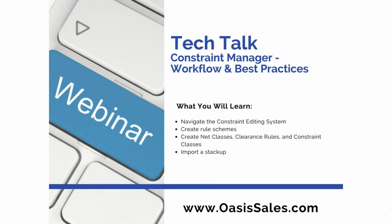So the Constraint Manager, a lot of people do find it confusing the first time that they look at it because there's a lot of information in there. Hopefully we'll learn today how to navigate that system, create rule schemes, create net classes, clearance rules, and constraint classes, and how to import a Stackup and see how that's going to affect our different constraints that we're going to define.